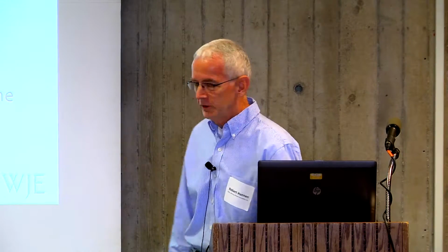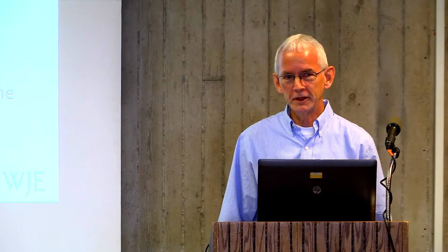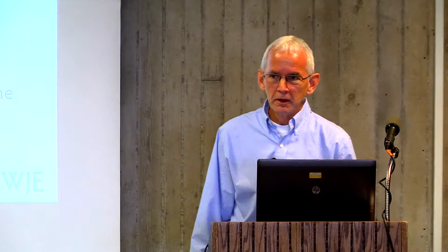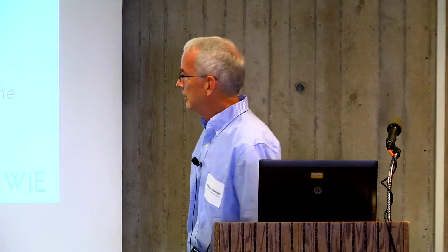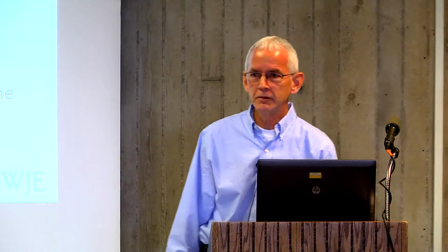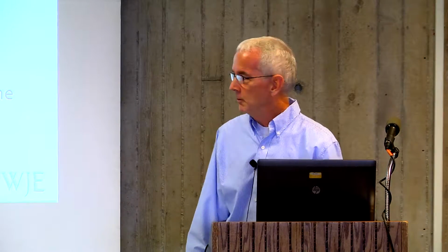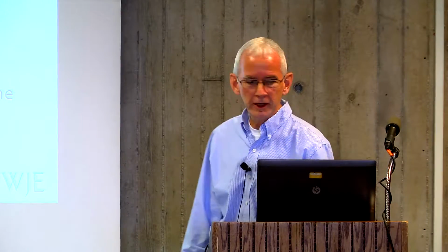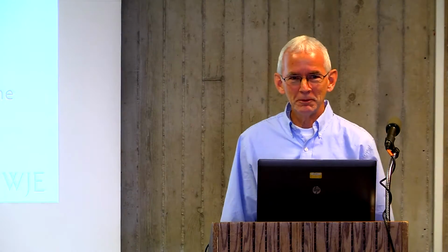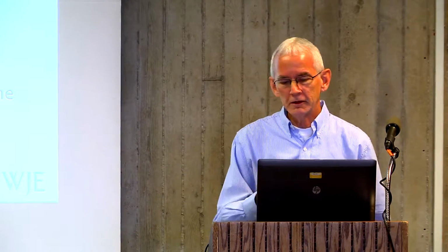So I was brought out to the site to look at it, and the contractor admitted that, yeah, we should have left that temporary casing in place. By the time the settlement eventually settled out, they had about 1.5 inches of settlement of that end of the building, and they discovered that the building was actually two buildings that were tied together, and it was no longer tied together. It opened up like a zipper going up the wall. So that was an effect.